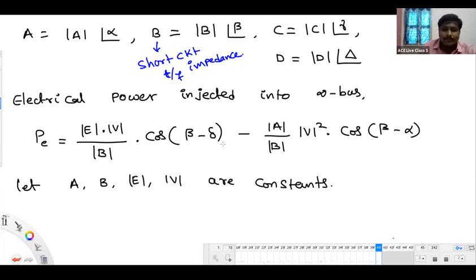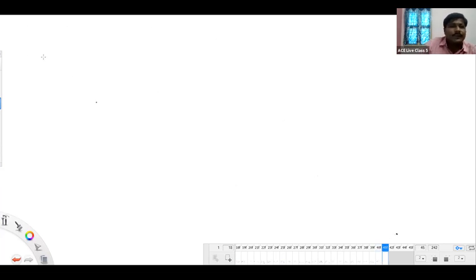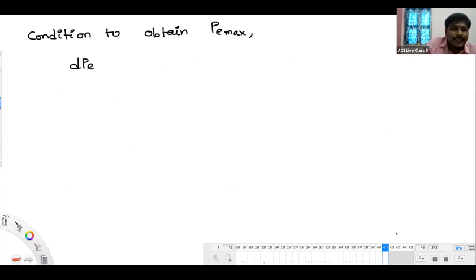All of you getting this? Please tell me. Okay, I will write in the next slide. Condition to obtain PE max, the maximum real power injected into the infinite bus, that is dPE by d delta equals 0.